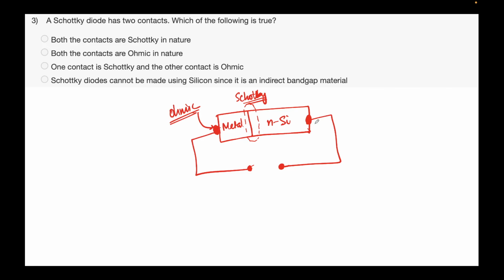Okay, and this one, as I told, I want the analysis of the region which I'm going to highlight in purple. What I don't want is all these outer things to play a role. So I should make all the other contacts conducting in both directions. They should have minimal role. They should not act as any resistance or any external thing. Essentially, we call them parasitics. Apart from parasitics there are other considerations, but I don't want them playing a role.